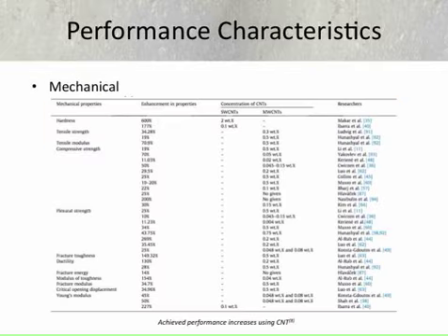And the types of mechanical performance characteristics can be seen in this table, and this is taken from a review paper for nanocarbon engineered multifunctional composites. And it can be seen that the introduction of carbon nanotubes provides very large improvements in, for example, the tensile strength and the hardness, I think, increased by 600%. Fracture toughness and ductility also saw improvements by over 100%.